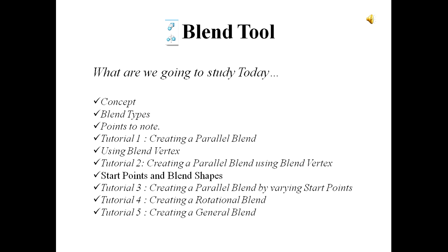So friends, what are we going to study today? Concept of the blend tool, blend types: parallel, rotational, and general, some rules which are to be followed in blend tool, tutorial cum exercise for parallel blend, operating blend vertex utility, what are start points in blend tool, creating a rotational blend, and finally an exercise on general blend.